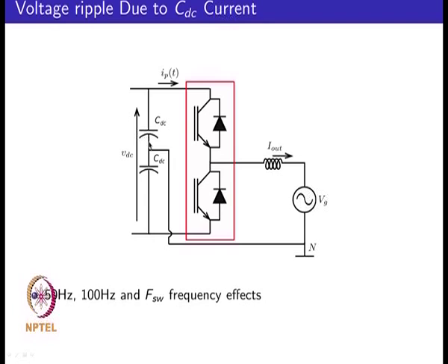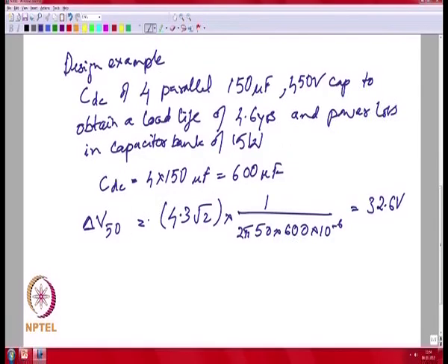So, the total voltage across the entire bank would not be affected by this 50 hertz, or at another instant the bottom might be minus 33 and the top the other polarity, but their polarities cancel. But on an individual bank basis, this is an important factor to consider. However, on a total bank basis, it is not observed. So, it is not seen on VDC.